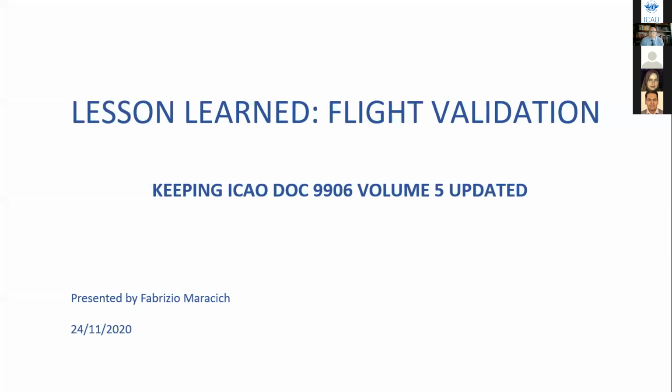Of course, in theory, if you design something according to the PANS-OPS, the Doc 8168 Volume 2, it should be safe by design. If it is a PBN procedure, according to 9613 and RNP AR 9905, then it should be safe by design. But now we are talking about databases and computers. So there is a need to check that the design matches with the real-world environment: obstacles, airspace, interactions, ground lighting systems of the airports, and all these kinds of things, because we were implementing new procedures.